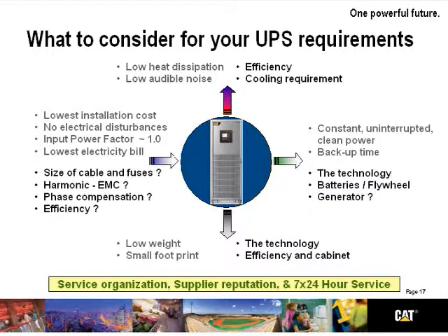Low weight is always important because we don't want to have to install reinforced floors or do something that's going to drive cost to our installation. We also like small-sized UPSs because we can then use the remaining square footage for profit-producing activities. Low installation costs. Why is that important? The less time a contractor has to spend on site installing a UPS, the less cost there is to a customer.